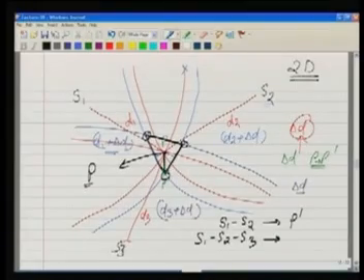The meaning is, even if our receiver has synchronization error, which will be there because receiver clocks are not very expensive, they are not very precise, still it is possible to determine the coordinates of the point accurately, because we are now making use of 3 points.